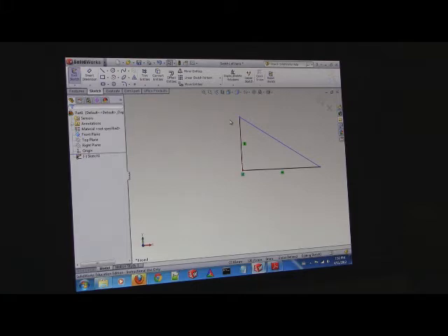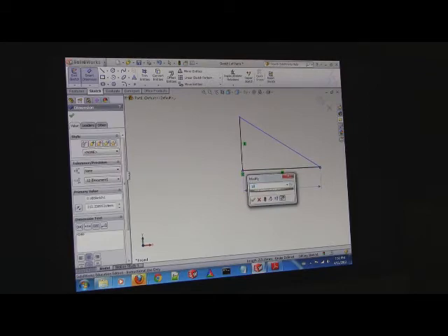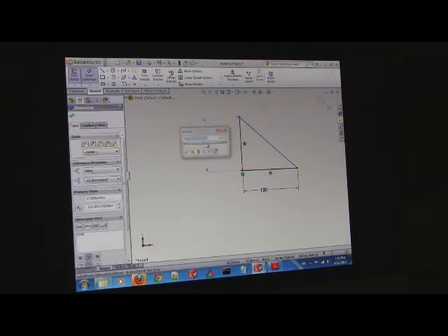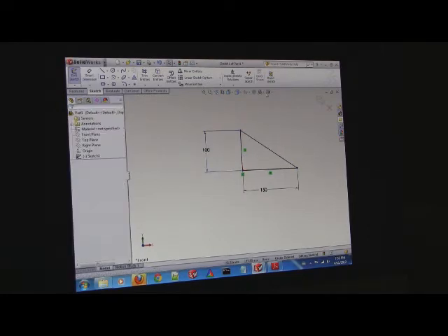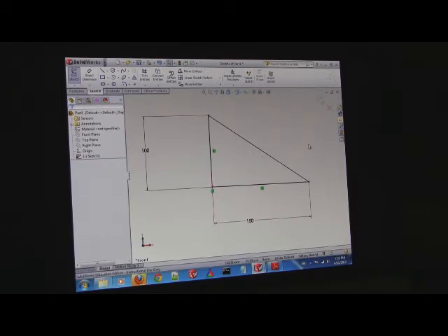Okay, so everybody have a triangle? Trudy, you might want to follow along. I'm going to show you some things that I'm guessing you haven't seen. Triangle? We good? Okay, so let's just go ahead and dimension the overall thing. Do smart dimension. The bottom is 150, and then the side is 100. Yeah, everything's millimeters. See how it's black now? So we're fully constrained. It's beautiful.